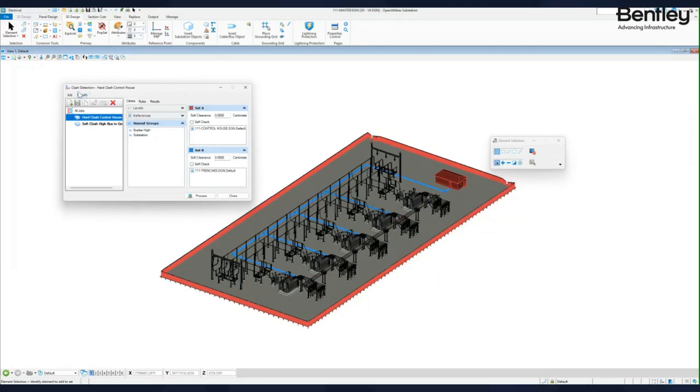And if it comes to the clash tool, we can simply clash between the different levels of the same design, between the different references, even including the point clouds and name groups. That means that I can group all of the trenches, or maybe group all substations, and so on and so on. And simply by this, here I will be self-checking the control house and trenches.